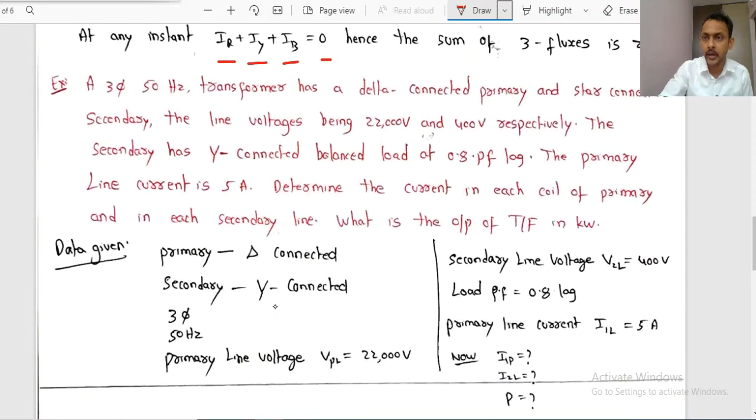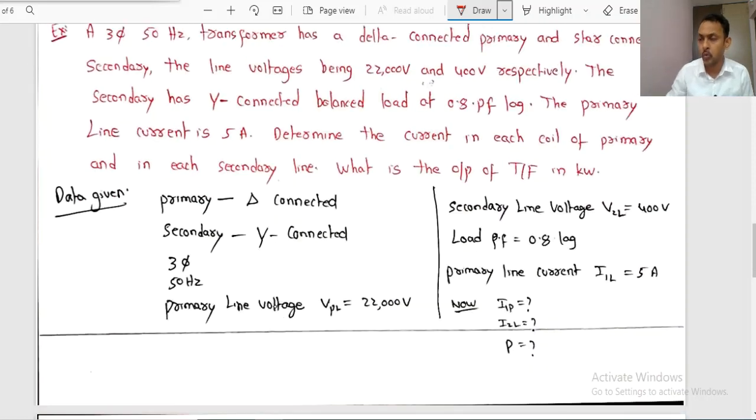That is the reason why, in order to avoid a huge amount of current flowing through the neutral wire, the systems are always to be maintained in the balanced condition. All the three phases are to be equally loaded. Utmost care is to be taken to maintain the system under balanced condition. If it is unbalanced, some current will be flowing through the neutral wire, right? Now let me discuss a small example.